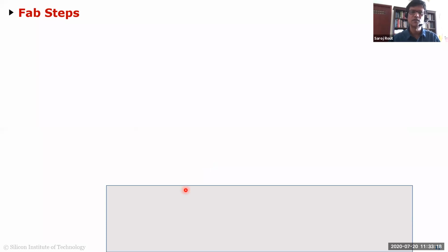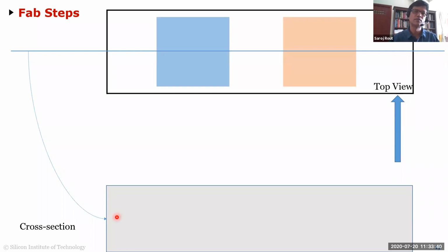So what you do is you first start with the base silicon, which is called the wafer, and typically they're about 1 millimeter thick, sawed down to sometimes 0.5 millimeter, 500 micron, or sometimes for some chips it has to be even thinner for noise coupling reasons and so on. So you start with this base material. So I'm showing you the cross section now, okay? And you send this layout to the foundry house.